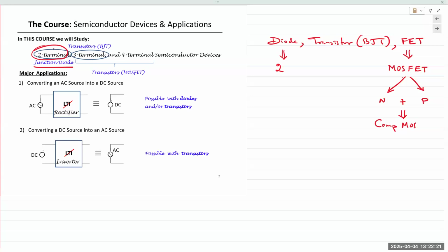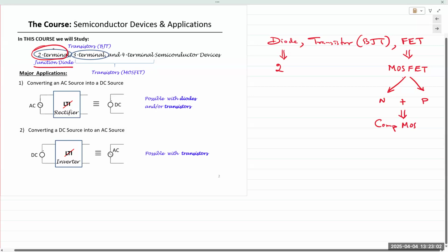The origin of these devices, or the predecessors of these devices, were the vacuum tubes. Okay, so in a vacuum tube, you had two electrodes. There was one electrode known as the cathode and another electrode known as the anode. They're sealed inside a small glass tube, hence vacuum tube, right? There's a vacuum inside. And then the cathode is heated with a filament. It gets so hot that it starts emitting electrons. These electrons float on the surface of the cathode. If you apply a polarity to the anode and to the cathode, let's say you apply a positive polarity to the anode, what happens to the electrons?